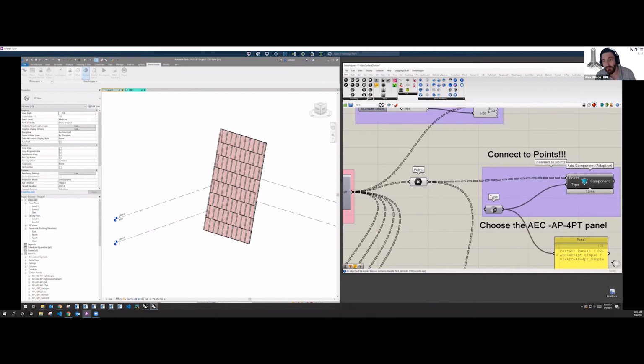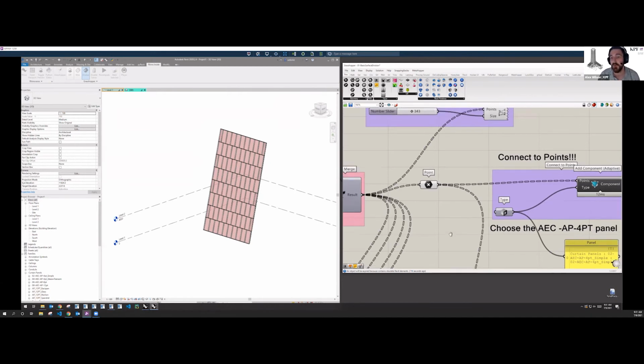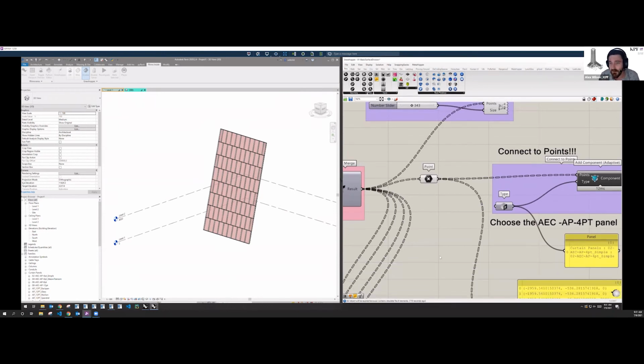So what that means is if at this point we designed this facade, we placed the panels, everything's looking beautiful. If we then decided to jump onto another facade and we're utilizing this same Grasshopper script, which is based off a curve, if we select a different curve, Grasshopper runs from left to right and then creates the panels at the end. It will delete the panels from the first facade as it creates the panels for the second.